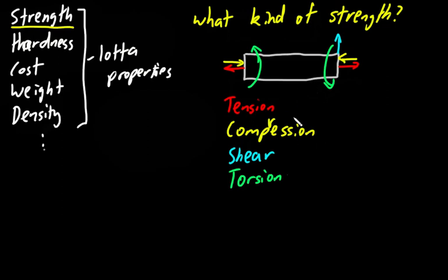But if you just press a rope together, it'll just go slack and doesn't actually hold up any loads. Whereas if you take a piece of concrete, you can push it together and it'll take on a pretty big load. You can stand on it; it will work fine. But if you pull it hard enough, it's much easier to break it by pulling rather than pushing it together.